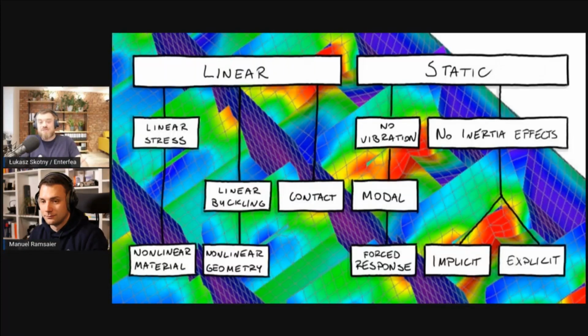Just because some solver names it differently, I'm not having this discussion. For me, it's nonlinear, clearly. If the contact is frozen, it's just two things touching. Whether you like to call it linear or nonlinear doesn't matter, because in the end, the effect is that two things can touch. And depending on the load, something can change in how they are touching. So clearly an iterative process, even in a linear analysis, if you have contact, there is an iterative process involved to see what is touching and what is not.